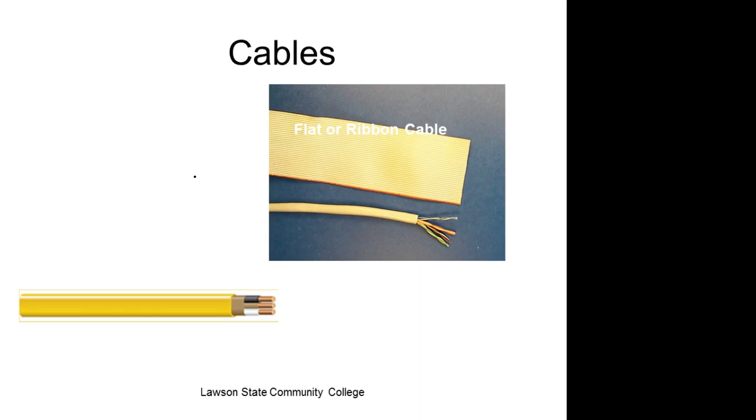So what we can do is put a breaker out there that if it's got a misbalance of like 10 milliamps, it'll pop between the hot and the neutral. And these are called ground fault circuit breakers. Ground fault circuit interrupter, GFCI.